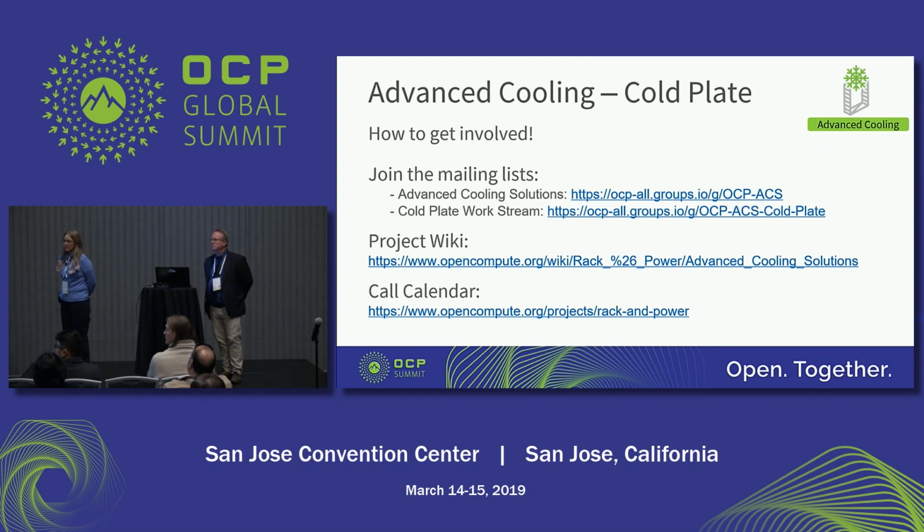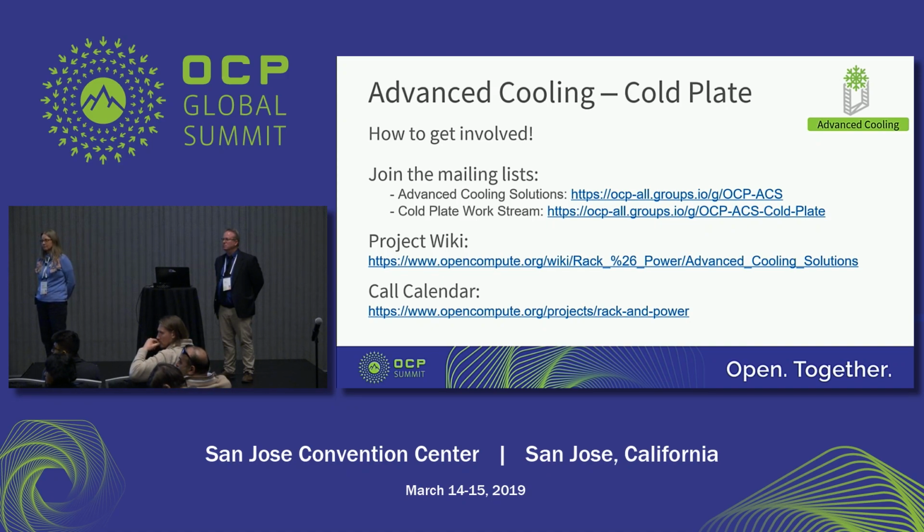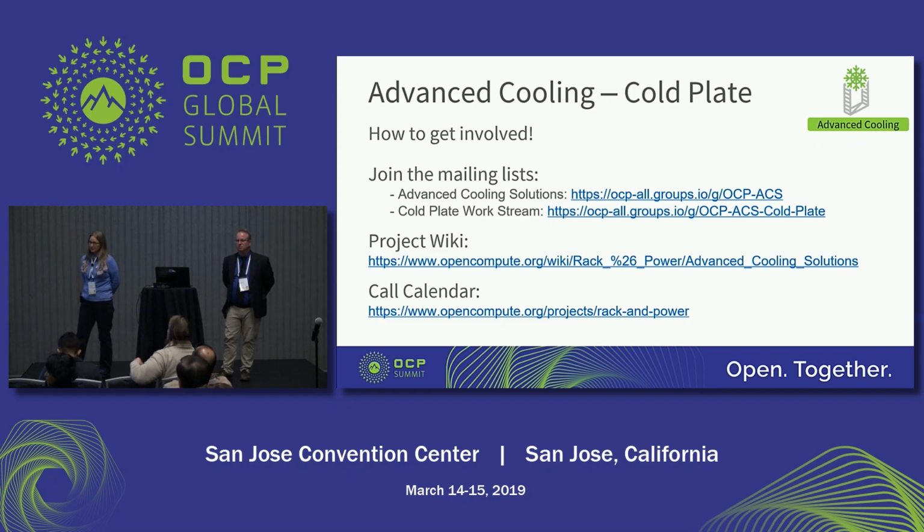So it depends on your location. You're kind of restricted in terms of the humidity and your environmental temperatures when you're selecting this, right? So there is some interface with the solutions that you're suggesting and the data center facility group in terms of HVAC design. Yes, it is. So these are the guidelines and recommendations that we're giving. It doesn't mean that it won't work in a different environment, depending upon your environmental conditions. All that you're really after is not to have condensation.